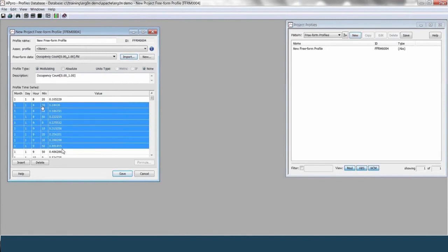Now you can see your 10-minute frequency data in a bit more detail. You know, we've got maybe 5, 6 decimal places here. You notice the time format's a bit different, where the way that Apache Sim reads this is it needs to have the date format in month, day, hour, minute. And really that's a key feature of ERGON, is the fact that it's really designed as a sort of pre-processing tool to take data, to process it, to really make it fit exactly in the way that Apache needs.